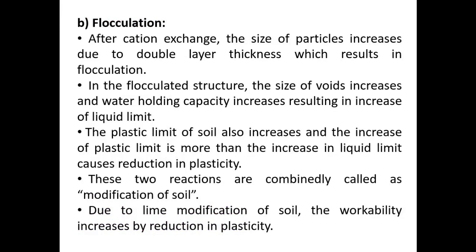Next reaction is flocculation. After the cation exchange, the size of particles increases due to reduction in double layer thickness, which results in flocculation. In the flocculated structure, the size of voids increases and water holding capacity of soil increases, resulting in increase of liquid limit. The plastic limit of the soil also increases, and the increase in plastic limit is more than the increase in liquid limit, which causes reduction in the plasticity index.